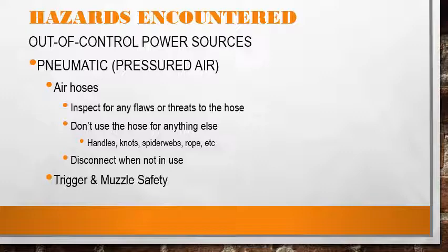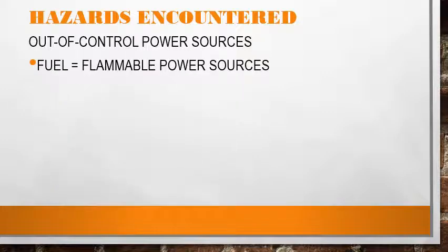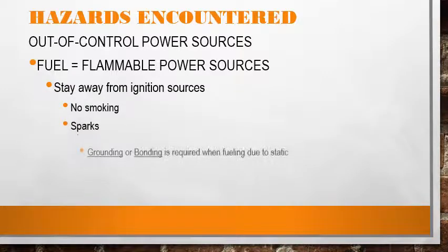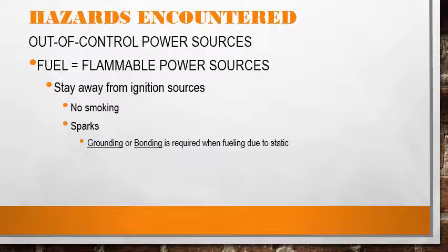Fuel sources can be explosive. Keep them away from ignition sources. Don't smoke while you're using a fuel-powered tool. When you are fueling, watch out for static. Make sure it is either grounded or bonded.